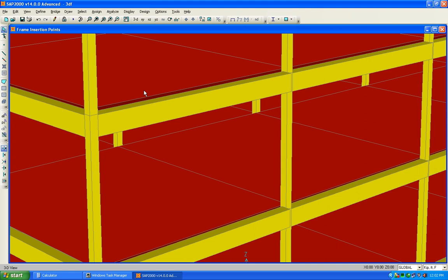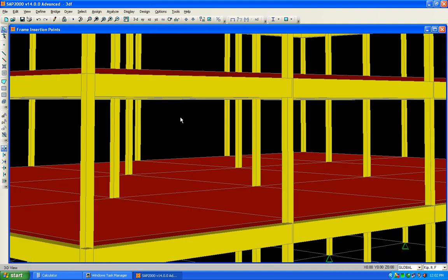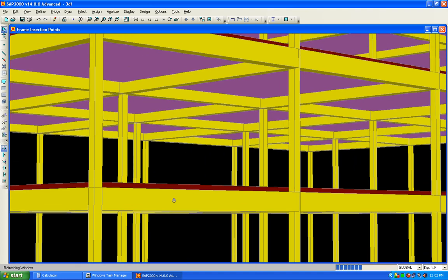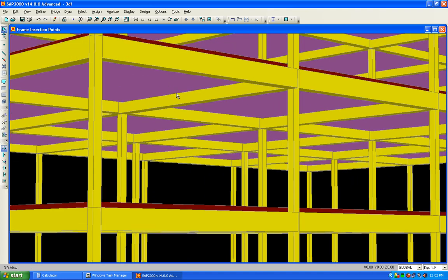Thickness is defined only in the formulas. Got it? So all the web is now right below the top of the slab. Now this is the model which we need. This point is very important when you make a slab-beam system in which you consider the T-beam below the slab. Now let's go back to our model.